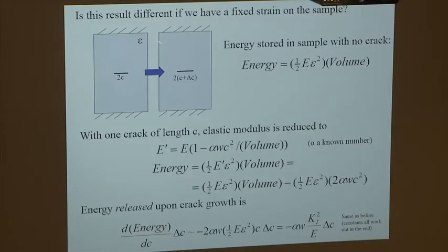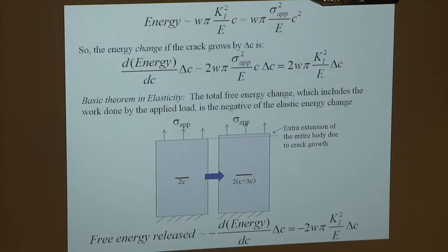But it turns out that if you had a fixed strain on the sample, you can think about the energy stored in a fixed strain case, and you can think about the elastic modulus change as having a crack, and you can get basically the same result as you get here. So whether you're doing applied stress or applied strain at infinity doesn't really make any difference.